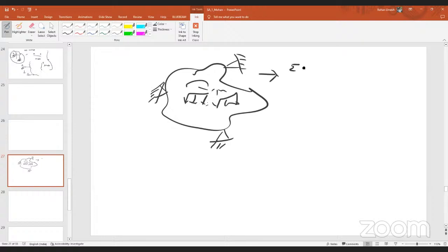That's where we are talking about equilibrium equations, Fx = 0, Fy = 0, and also Mz = 0. If you're directly looking at a structure, will they be visible on the structure itself? No, right? So we have to represent them. Wherever there is a possibility of applied forces or reaction forces, we have to represent those forces and then understand whether they are equal to 0 or not.